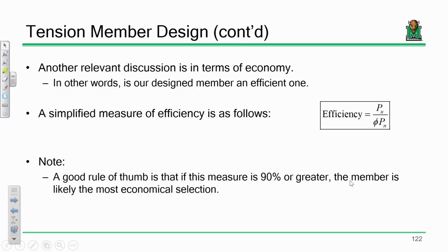Whereas if I had a W10 connected to another W10, well, I could slap a plate up here, slap a plate down here, and bolt them down. Having the members have similar depths makes the connection make a little more sense. So everybody okay with that? So it's a little bit, I don't want to say outside of reality, but I'm limiting that to where we all get the same answer.